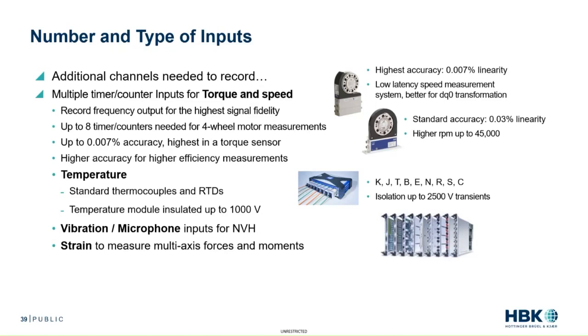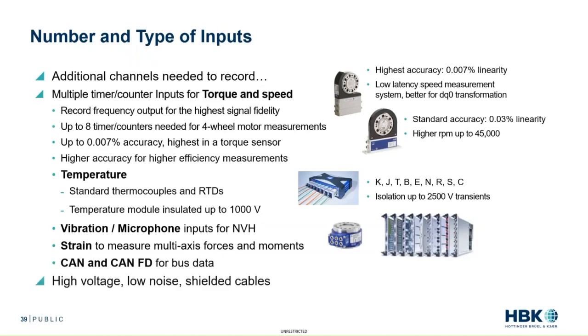Could be strain measurements that you want to measure multi-axis forces and moments on a particular structure. Maybe you need to record CAN or CAN-FD bus data from a vehicle, for example. And ideally, you want to have high voltage, low noise shielded cables. So really to provide a full, complete solution, ideally the power analyzer should provide the ability to supply some high voltage, low noise shielded cables for getting your signals recorded with the highest fidelity possible.